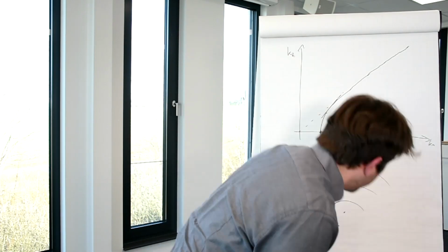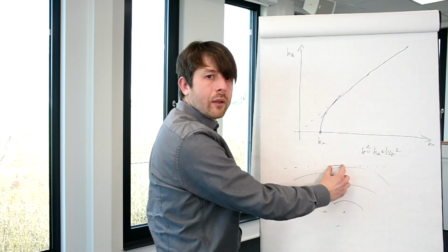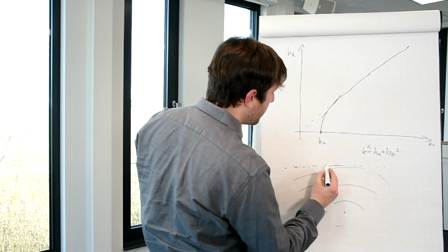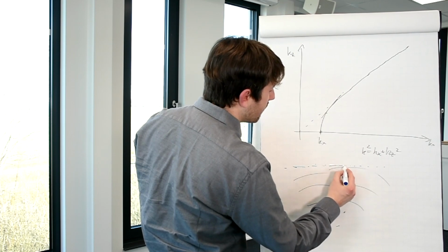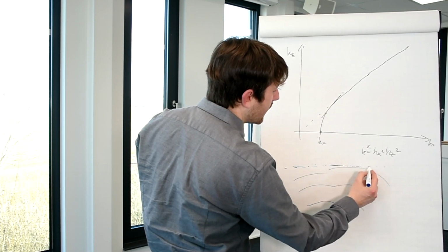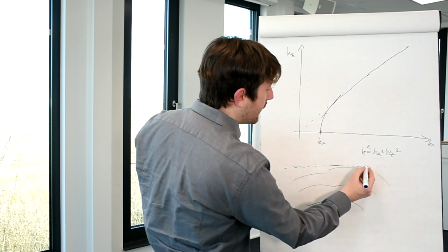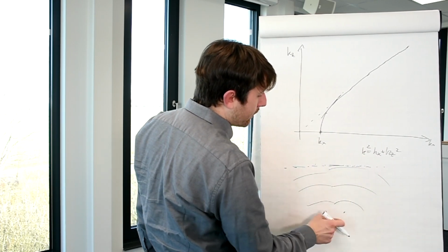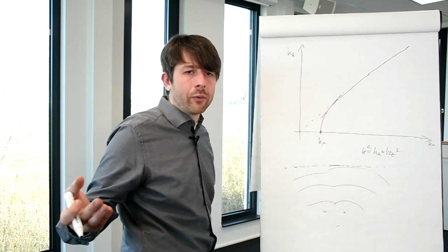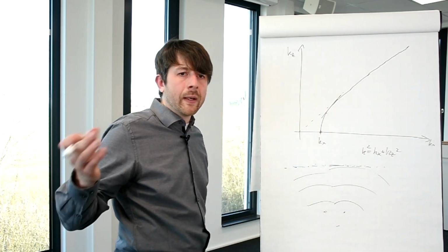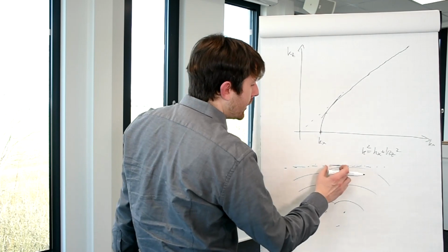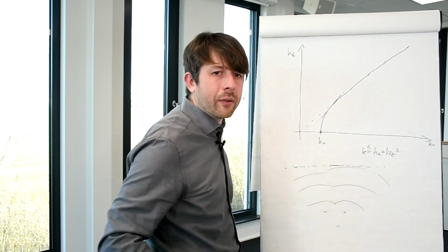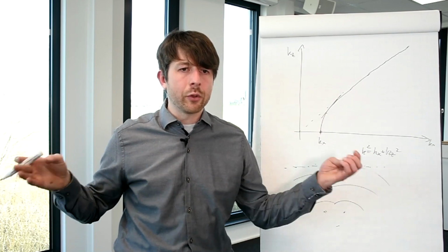So you don't measure a dense antenna array, but you measure some part here, some part here, some part here. So you have a random distribution of antenna positions, which is wide, but has gaps. And you can interpolate these gaps by taking the preliminary knowledge that my image cannot look arbitrary, but has 3 scatterers, 4 scatterers, something like this. And that works pretty well. Just measuring with a small array and then inventing resolution doesn't work, because you don't have this information.